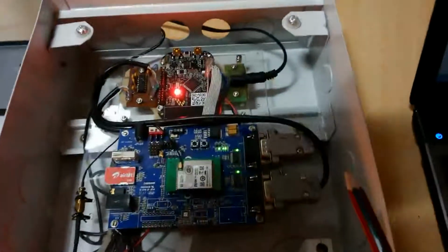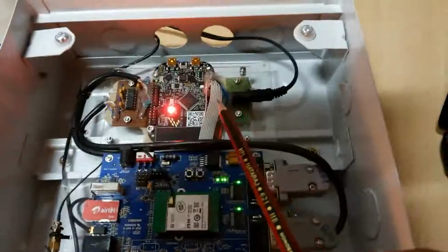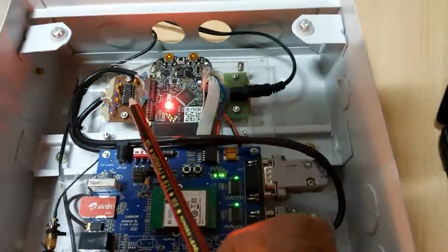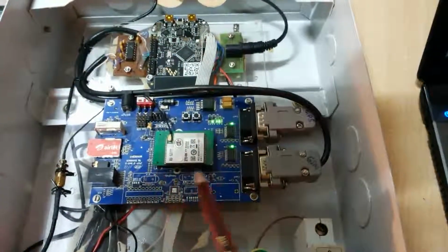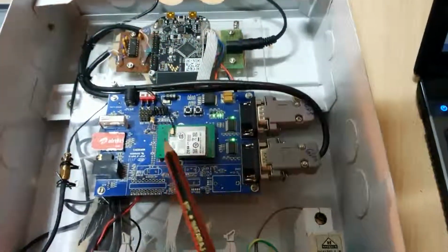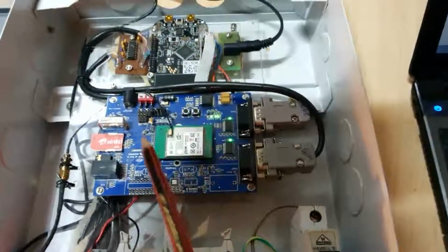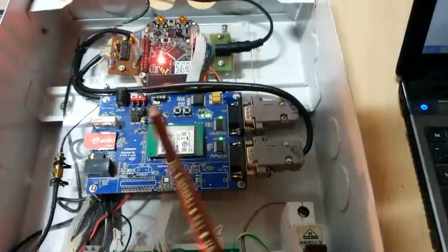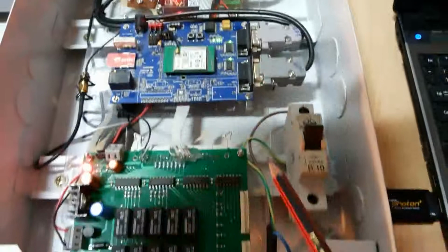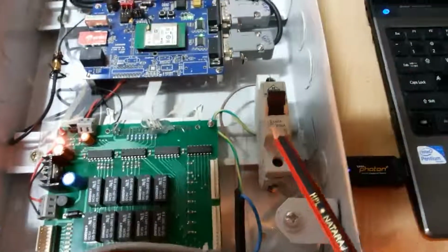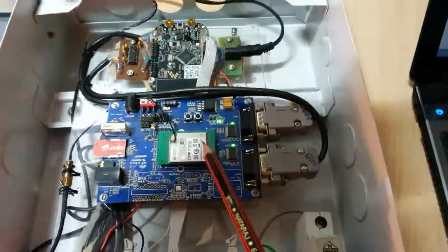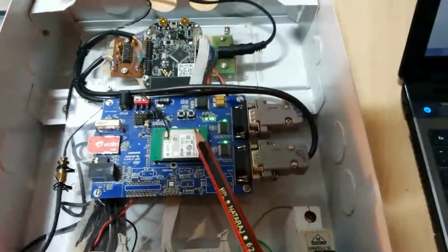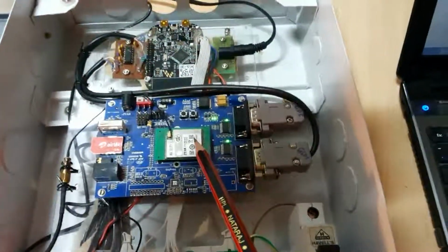Here, the core of this is the Freescale controller, which you can see, and there is a UART board over here, and this is interfaced to a GSM board, which is the main communication interface to this IEDS consumer unit. And you have the load relays over here, and this is the master circuit breaker. When the IEDS is first installed, this particular GSM interface connects to the control station, and if